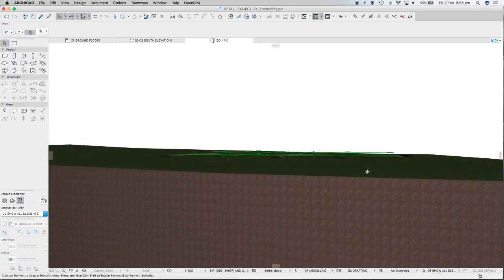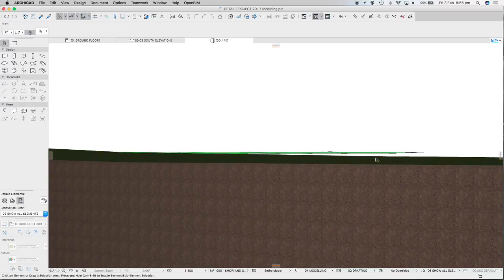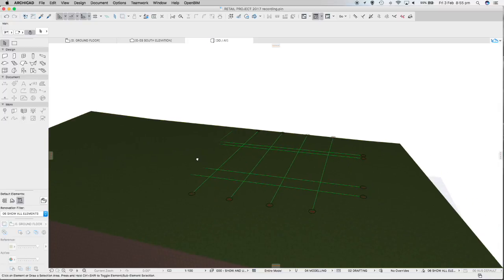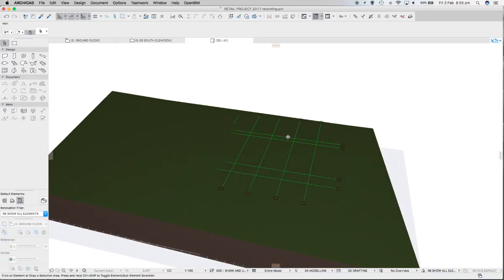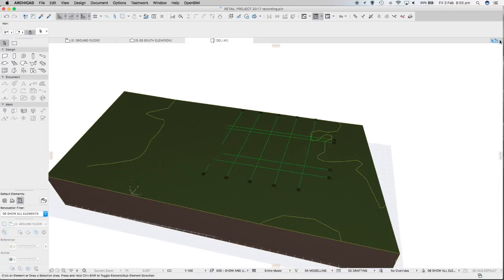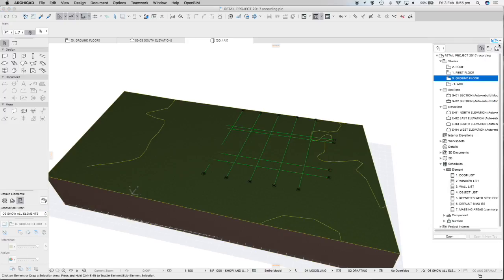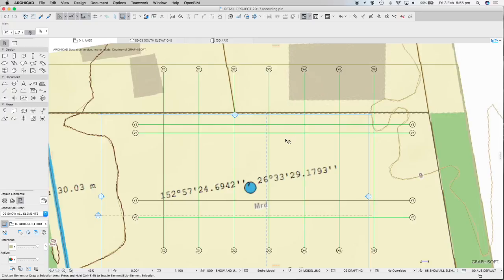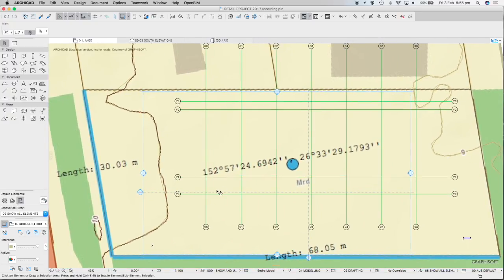Now, even though the ground is sloping, as you can see, it's floating up above here, and then the grids are bearing into the ground in that end. So that's a good starting point for us all to be at. Okay, so I'll do the rest now from, I think, AHD. So opening up the project browser and double clicking on -1 AHD. I think I'll create some offset lines around the outside of the outermost grids. I think we'll go about 1.5 meters in all directions.